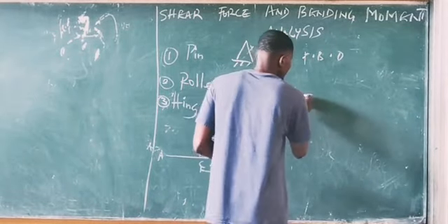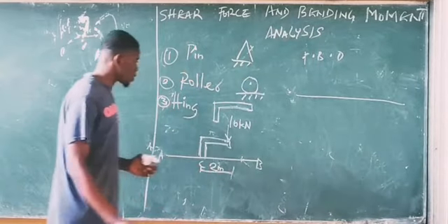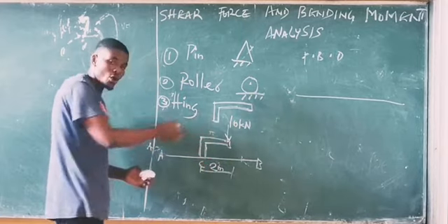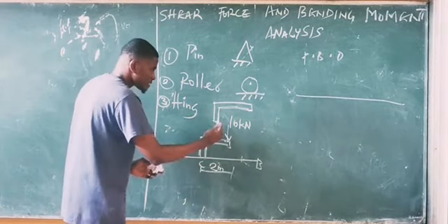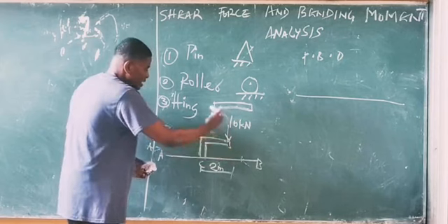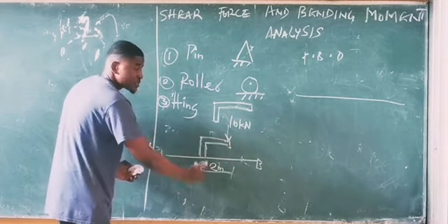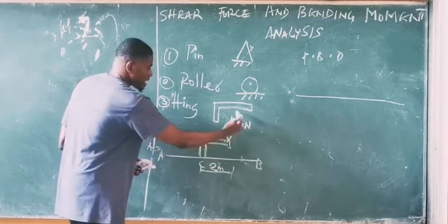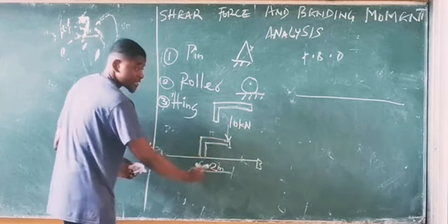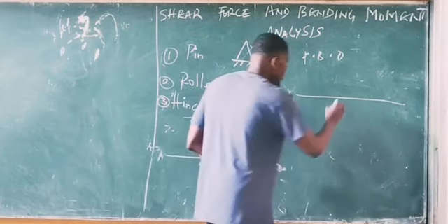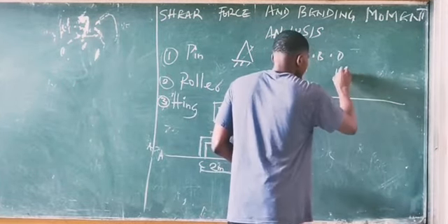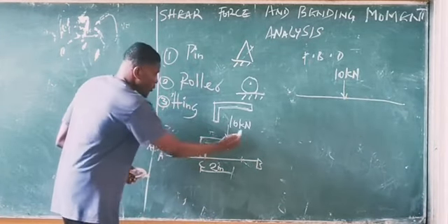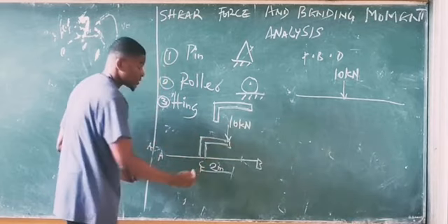So the free body diagram, FBD, for the hinge support becomes as follows. Notice that if I pull the door knob, the whole weight, which is this force acting on this point, is felt at the hinge. So at the hinge, at point C, we already have 10 kilonewtons having an effect at that point.